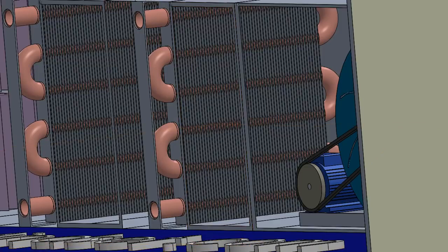So to improve the heat transfer of this heating or cooling coil, we put these fins all the way across the pipes, and that allows the heat in there to transfer and conduct through these thin sheets of aluminium, maybe stainless steel or something, and that travels across, and that allows the air that's passing through to capture that heating or cooling energy, thermal energy, off of these fins and bring that away.